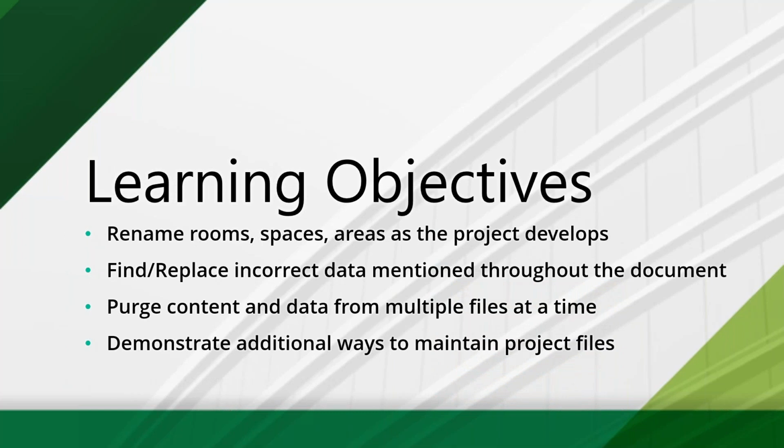Hopefully, when this is done, you understand how to set up a bunch of views and sheets, the process of renaming those elements in an existing project if that was started previously, or to help implement the standard if the view creation process isn't 100% what you need it to be.